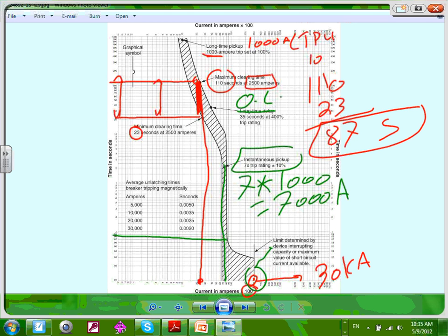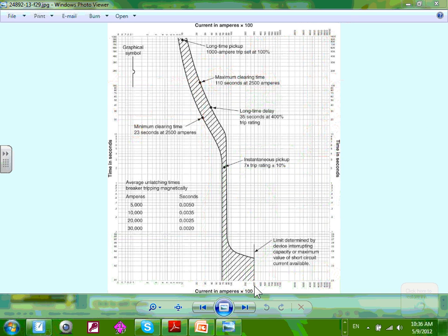Any comments, any questions? Tomorrow, guys, or Friday, we will be dropping these. We will be putting them together for our system. The 4,000 amp switchgear that we did, you're going to pick up a circuit breaker from Cutler-Hammer, grab it. It will come with a curve like this, and coordinate that curve. So that's the coordination for this breaker. Okay.